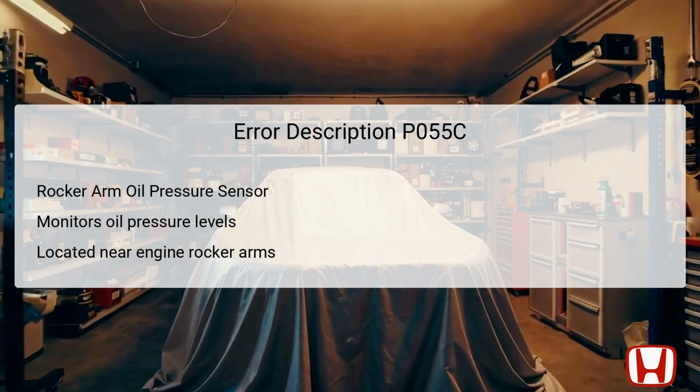The error P055C specifically pertains to the rocker arm oil pressure sensor, a component designed to monitor the oil pressure within the engine's rocker arms. This sensor plays a crucial role in ensuring optimal engine lubrication, directly influencing engine performance, efficiency, and longevity. It is typically located near the engine's rocker arms, which are critical for valve operation in the internal combustion engine. Proper oil pressure is necessary for the rockers to function efficiently, and any discrepancies or low voltage signals can lead to engine performance issues.